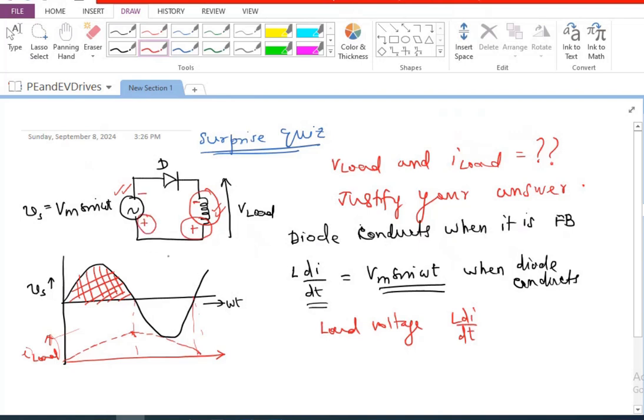There will be a tug of war between these two. And if it so happens that the inductance is winning over, then the diode will be still forward biased. So you will have this voltage completely coming across the inductance. So I should have even the reverse half cycle completely being translated at the output also.